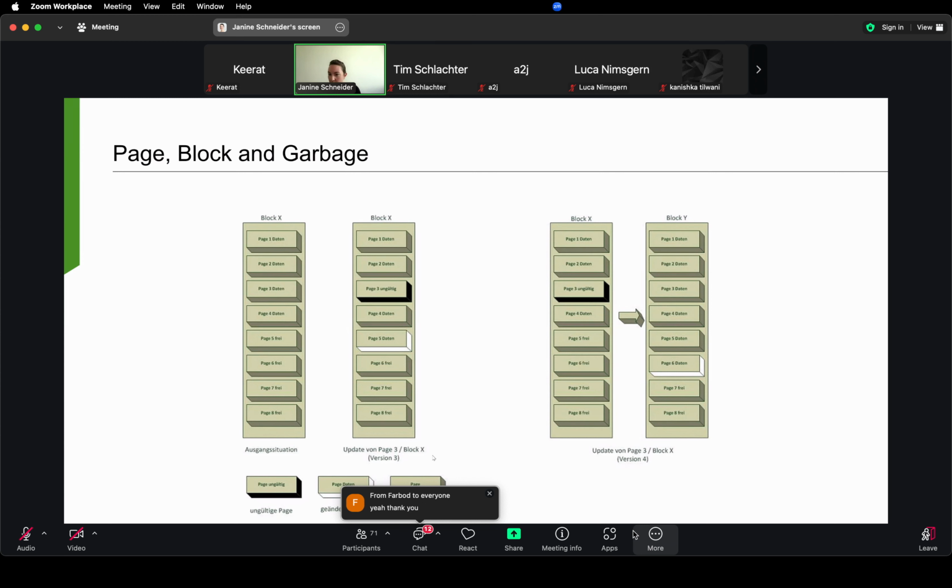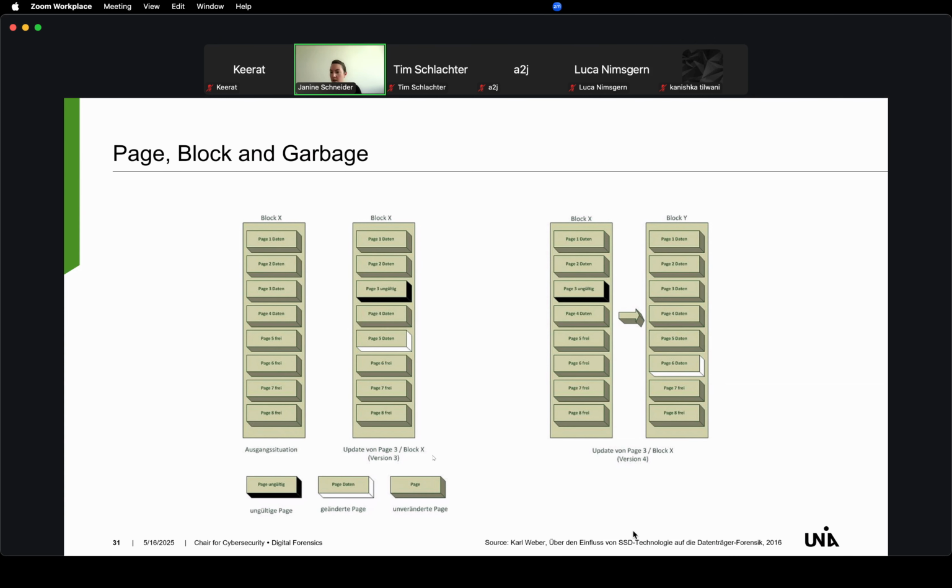For clarification, we can write to a page that is empty but not overwrite stuff in it directly. Why does it not just write zeros and ones to the same page again? Yeah, according to these strategies, in order to update a page, you have to write it to another page, because your smallest unit that you can write is a whole page. You cannot take one specific bit or byte and change that.